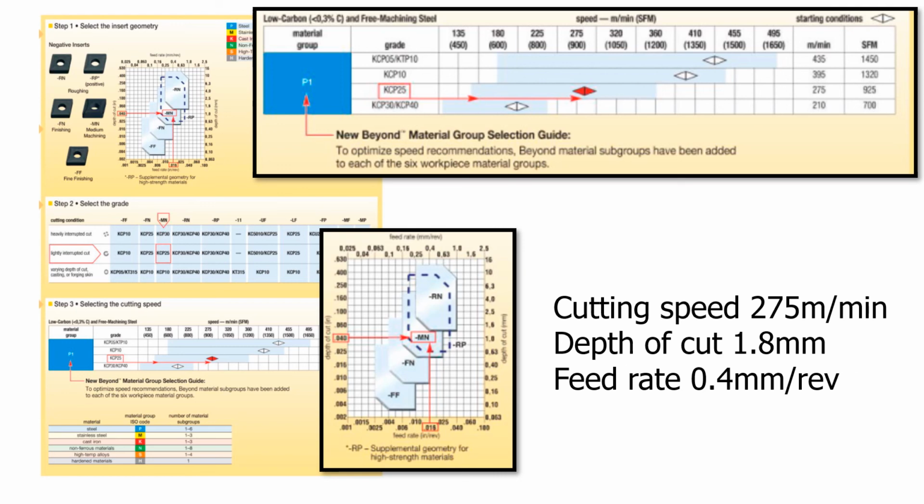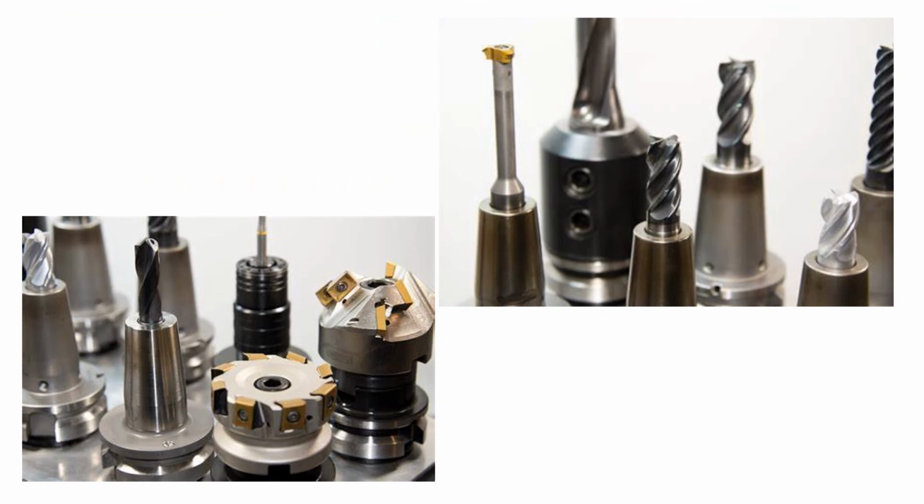That's the recommended feed rate per revolution to introduce the tool through the material. Always refer to tooling manufacturers' data sheets for correct cutting data to get the best efficiency and value for money out of the cutting tool.